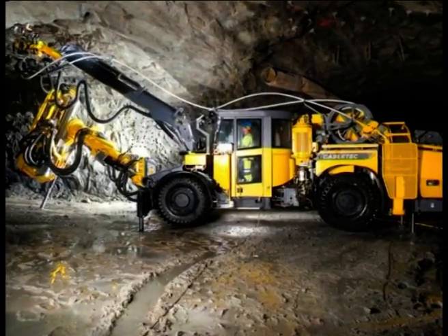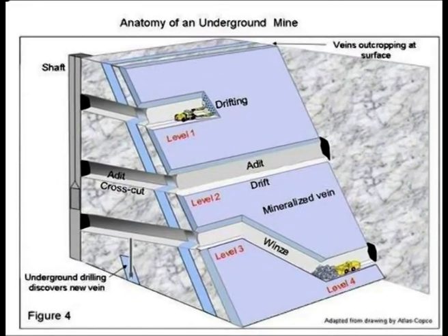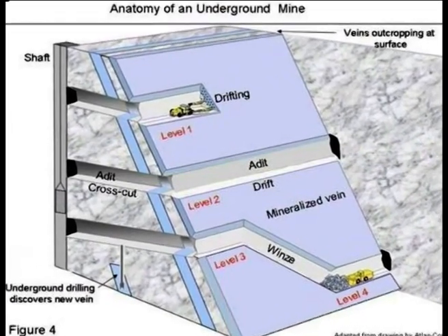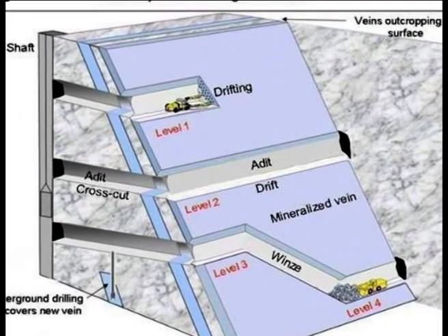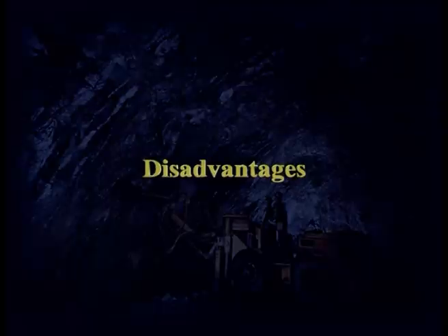The opportunity to use old mined out stopes as a repository for waste rock blasted in order to access further new stopes. Such a process is known as backfilling old workings and helps stabilize the ground, reduces the cost of haulage and helps avoid falls of ground or rock bursts.